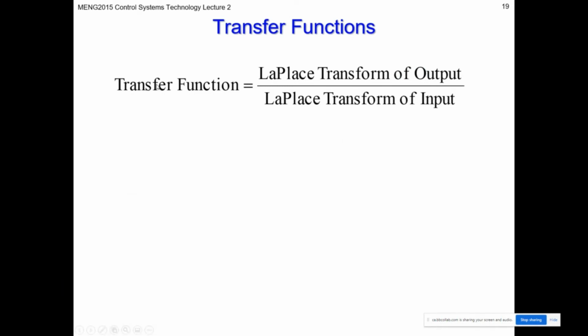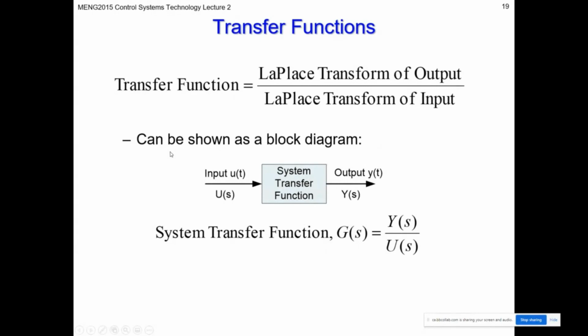Transfer function. Now we've got our system, which is really determined by differential equations. Now it's expressed in S terms in the Laplace form. You can actually get the transfer function of the system, and that's the output divided by the input. And when we have a transfer function, we can then present our system using a block diagram, and our input multiplies by our transfer function to get our output.